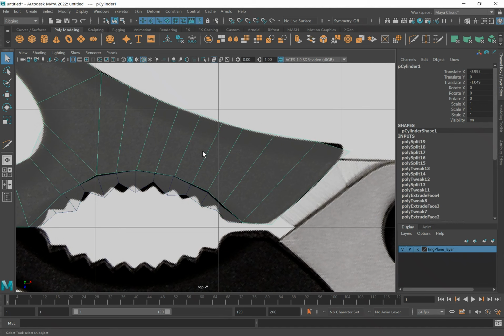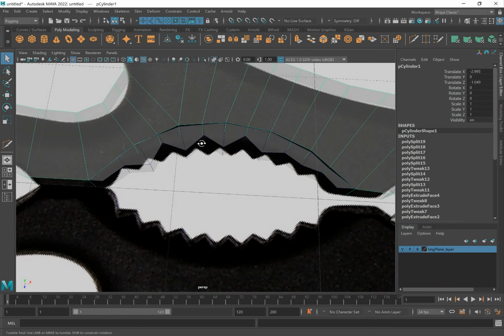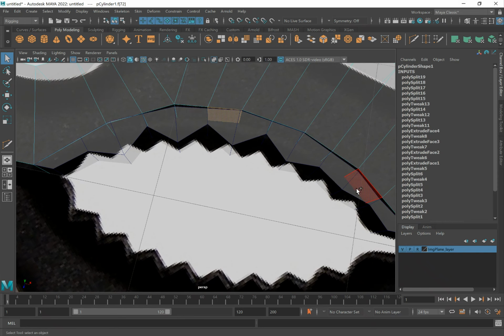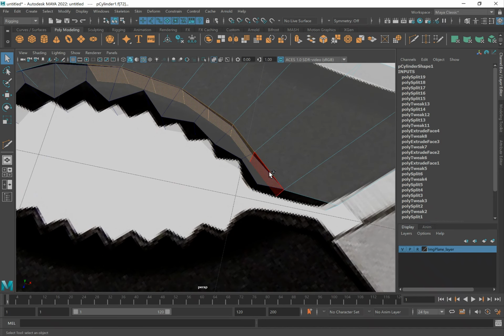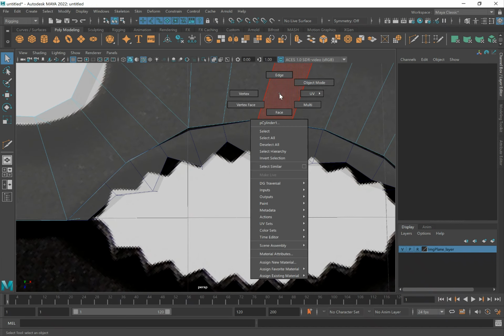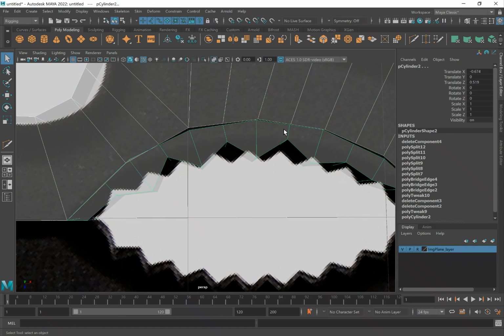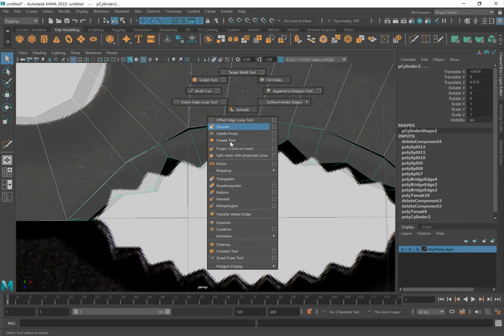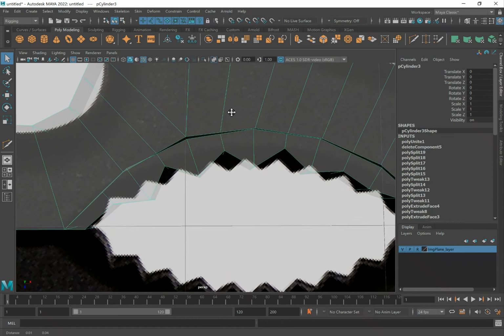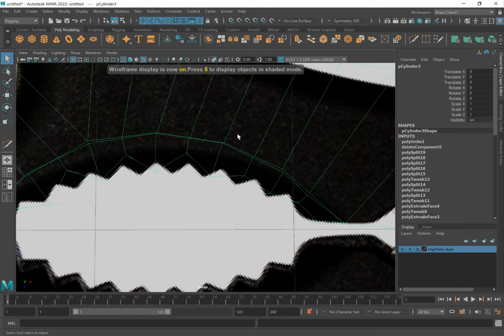Okay, and actually before I do that, if you recall, these objects' faces at the front here are still not removed yet, so I will need to remove these faces. Okay, so backspace again after the selection. Then I'm gonna select the two objects here. Okay, shift right mouse button, combine. Okay, so once it's combined, a few things that I can essentially do.